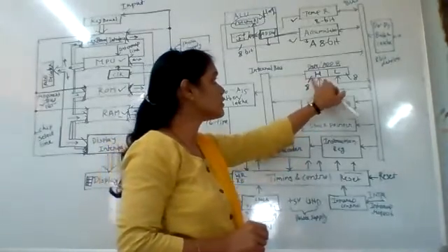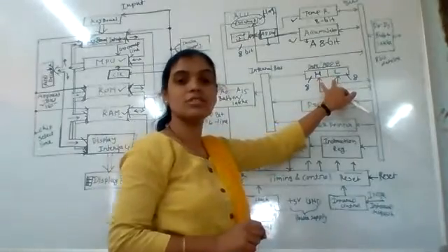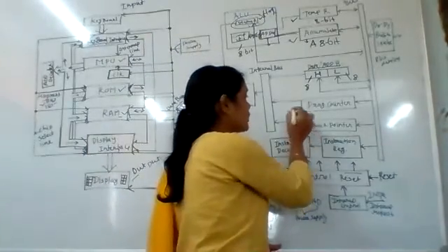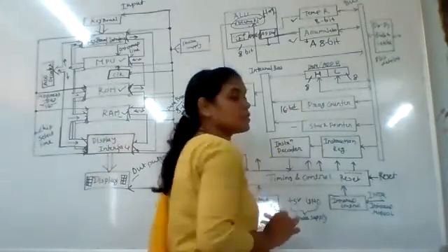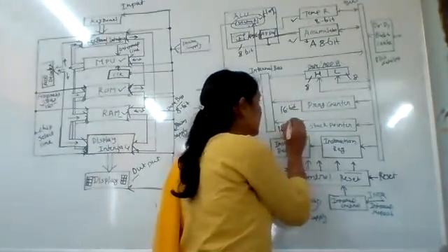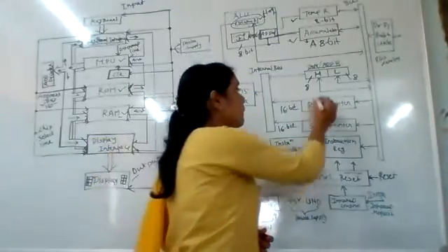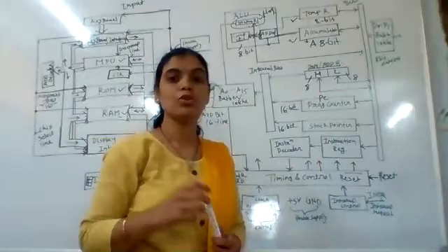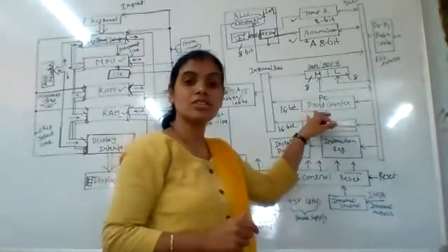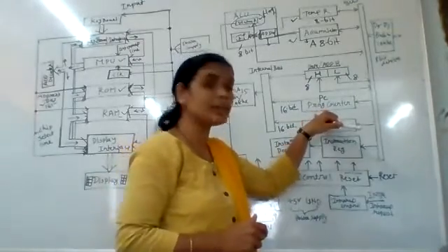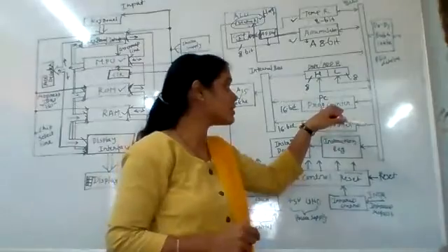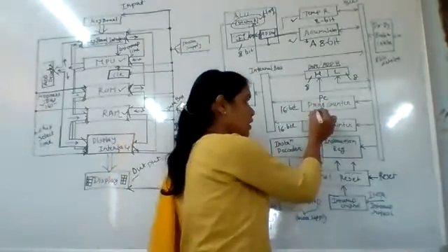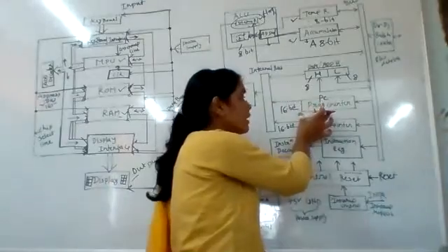When we use this register in pair, a 16-bit address is stored in it. Next is the program counter. The program counter and the stack pointer are both 16-bit registers. The program counter, or PC, is used to point to the address of the next instruction to be fetched from memory. When one instruction is fetched from memory, the PC is automatically increased to point to the next instruction. In simple terms, the program counter stores the address of the next executable instruction.